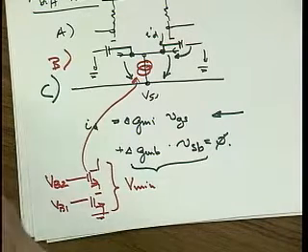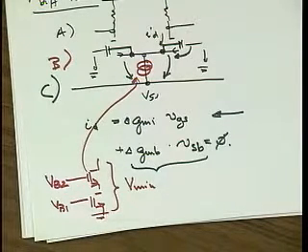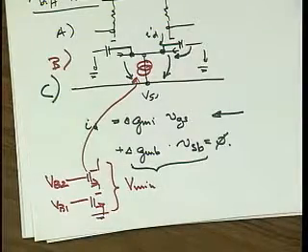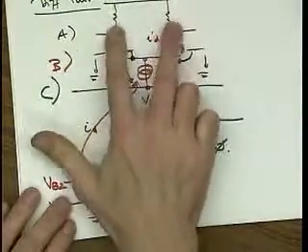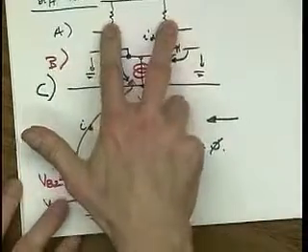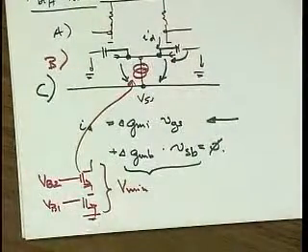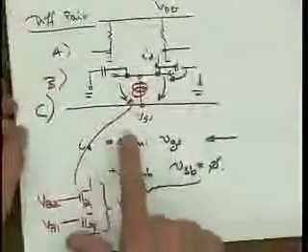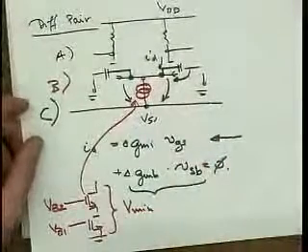Well, we would have to calculate this, right? Resistors typically come out to be humongous, and that helps matching, right? Big means we get more averaging, so the matching's better. Now, very rarely do we actually use resistors here. More often current sources, and then it's transistors and transistors. About the same. I'm not even sure whether I have the resistor matching data. We'll look at how to calculate stuff like that later on.